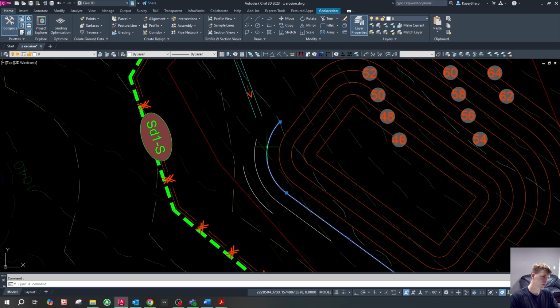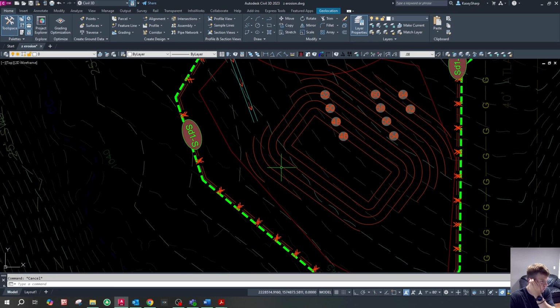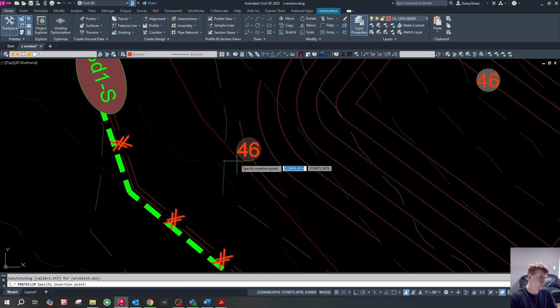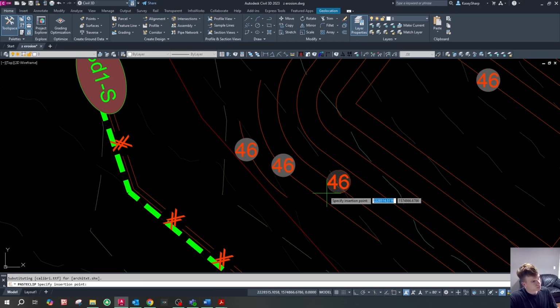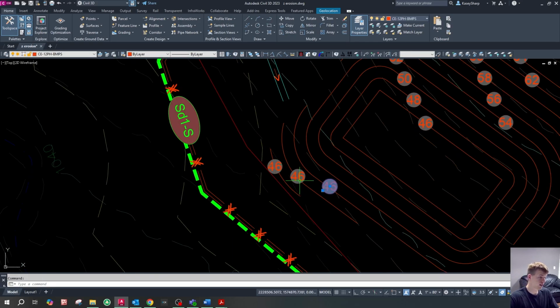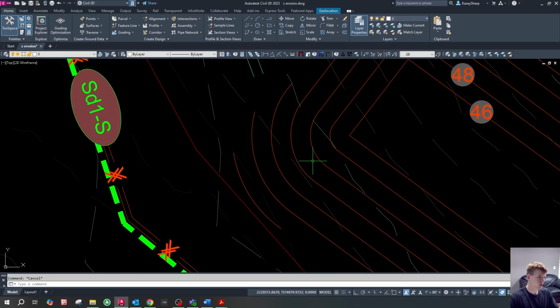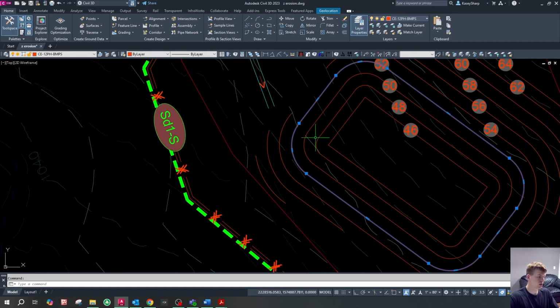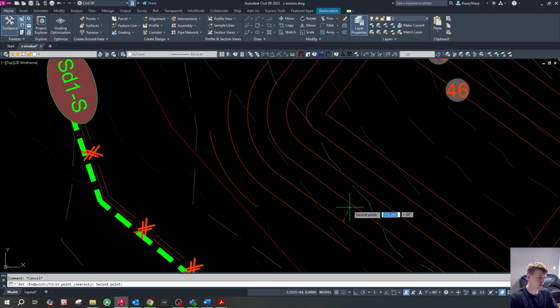It meets the minimum required sediment storage provided. So I'm going to go ahead and I'm also going to provide, working up the side of the berm here, I'm going to give elevations going up. So we're going to have a berm width here. So actually, I kind of lied. We're going to have to regrade this. So this is our top contour here that closes, and then we're going to have a berm width here.